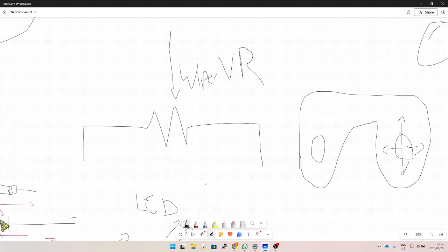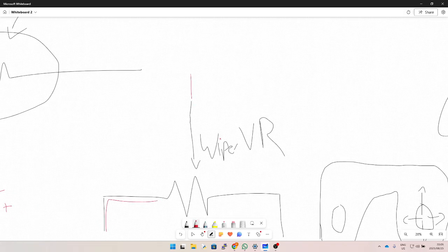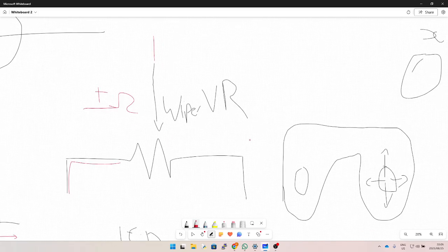Now, this is how volume controls on speakers are commonly wired. When only two terminals are used, for example, this one and the variable wiper here, it functions as a resistor where you can change the resistance. If I supply 5 volts there and 2 amps, and my resistance is 220 ohms, whatever. It's a resistor where instead of having a set number of ohms, you can make it larger or smaller based on where the wiper is. Did I explain that? That's everything I missed in that section, right?